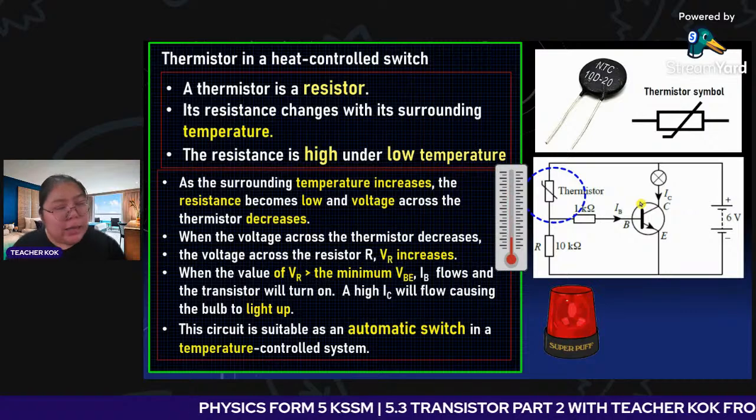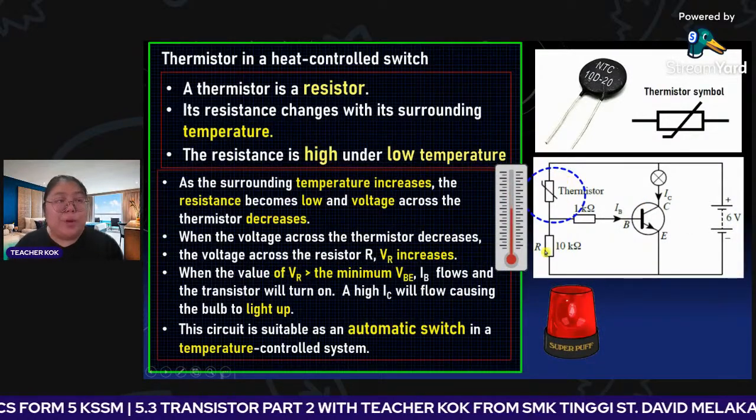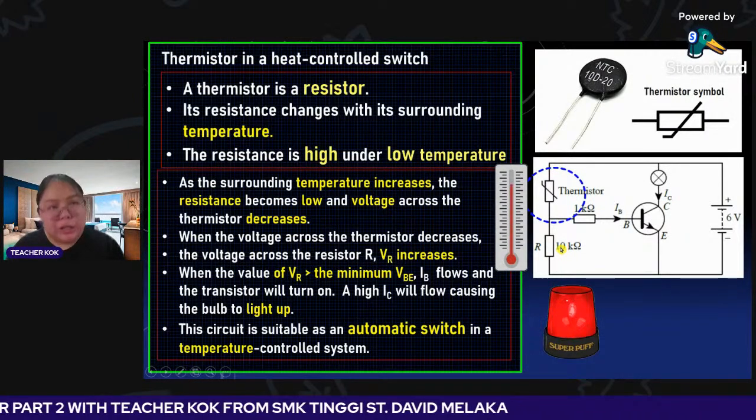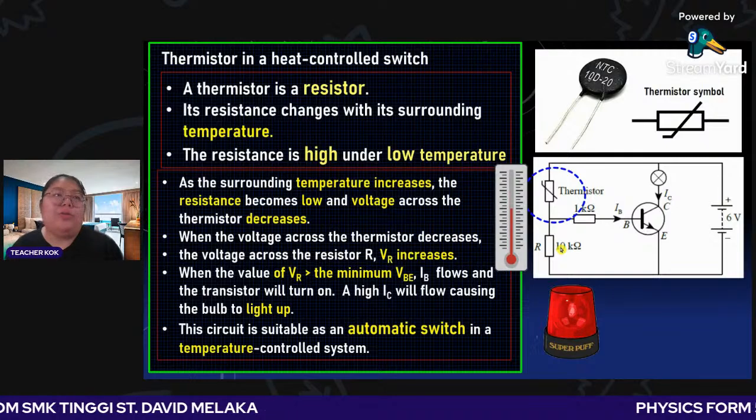So if I put the thermistor at the bottom, what happens? When I put it at the bottom, the siren will be on when the temperature is low. When the temperature is too low, the siren will be on.